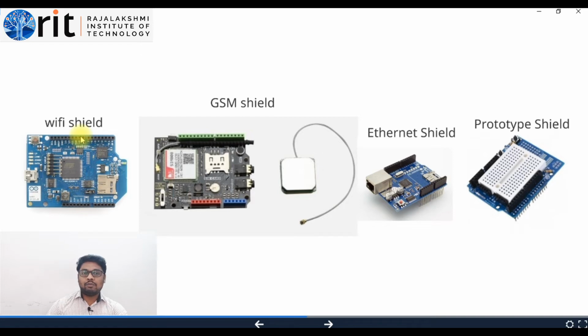And nowadays we have one more alternate board for the Arduino, which is NodeMCU. NodeMCU is the same as Arduino, and a little bit smaller as well. But this board can integrate both Wi-Fi as well as the existing Arduino architecture. The only disadvantage is that the NodeMCU has only one analog pin, but in Arduino nearly 6 analog pins are available. So you can go with that option, or else you can still use the Arduino board, and mount this Wi-Fi shield on top of your Arduino, and you can connect to any internet Wi-Fi services.